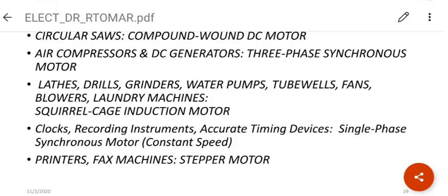If input is an electrical signal which is a pulse, that means some signal for some time, then no signal for some time, then signal for some time, and so on, then the motor would move through, let's say, 1 or 2 degrees, then it will do nothing until the next pulse comes in. This is called a stepper motor. In printers and fax machines, this motor is used.